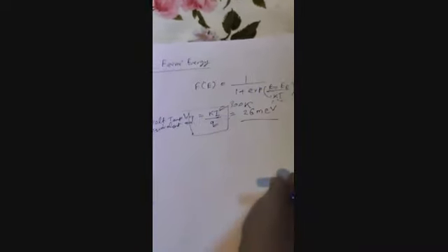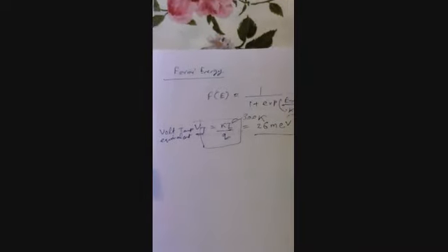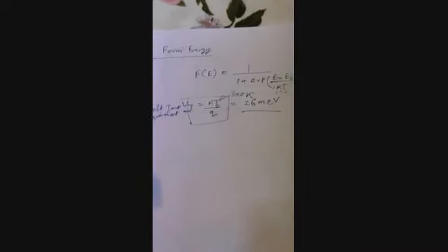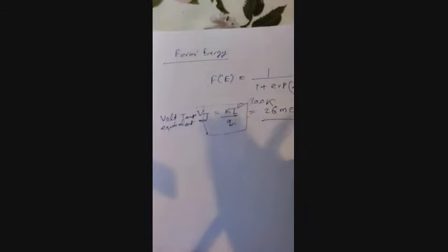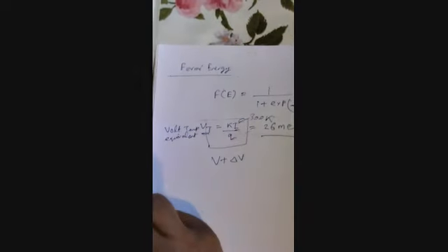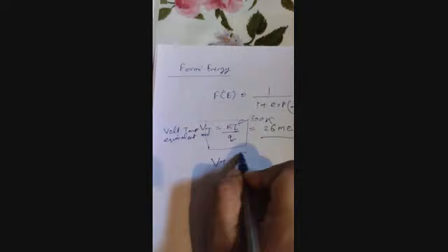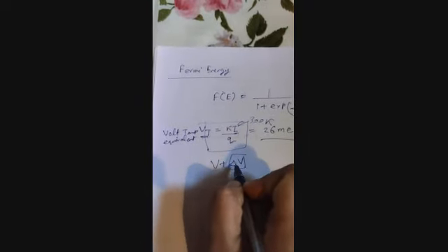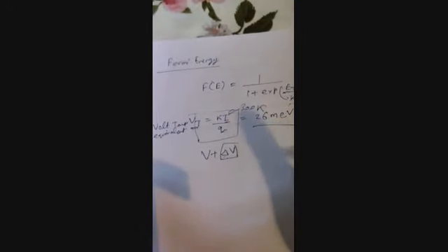This is the basis of any electronic device small signal model. What is a small signal model? A small signal model means a model for small perturbation, for small change. Like I have applied a voltage V across a diode, and now suddenly I change it to V plus delta V. So the change across the diode is delta V. Depending upon the rate of change of the diode with delta V, how my diode is going to behave corresponds to the small signal model.